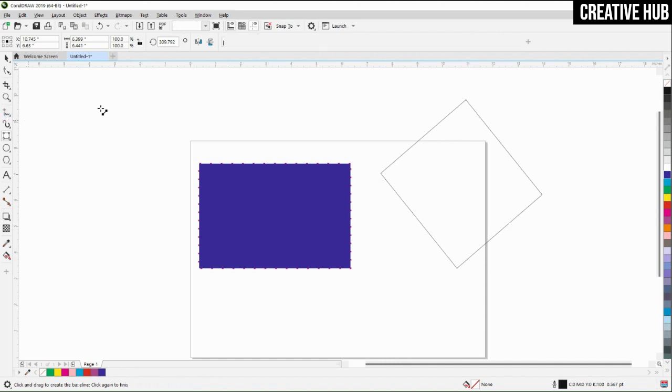Let's say that today we have a line, this is a 2-point line, and I want to have a rectangle just attaching to this over here. So this is how I'm going to do it. My alignment and rotation are all taken care of by one simple tool. I do not have to rotate it at some really weird angle just because my line is here. So that's where this tool comes very, very handy.